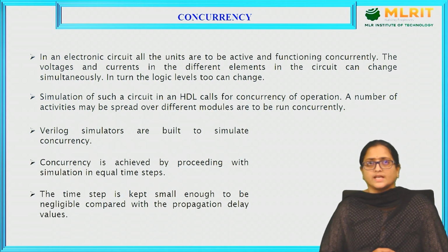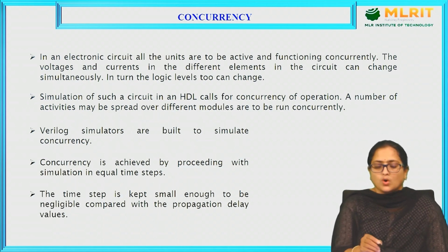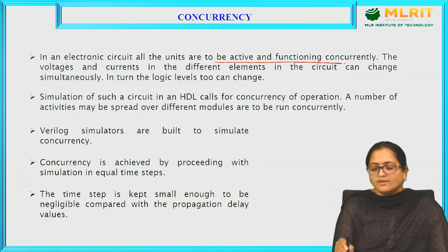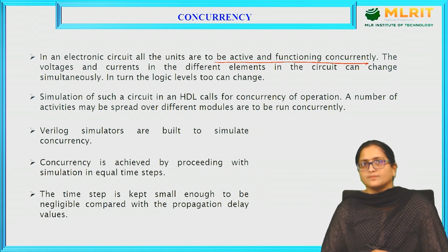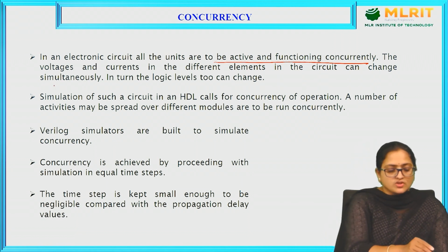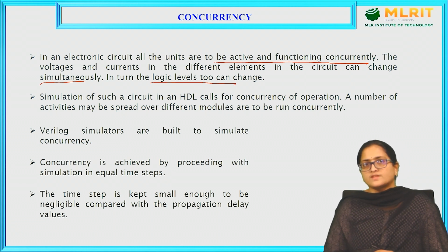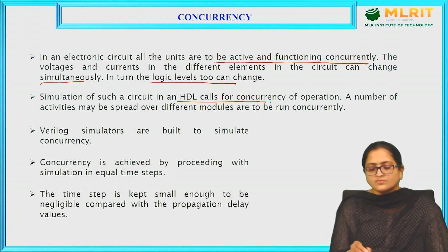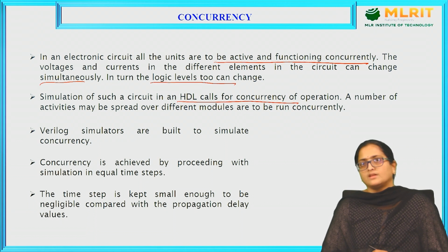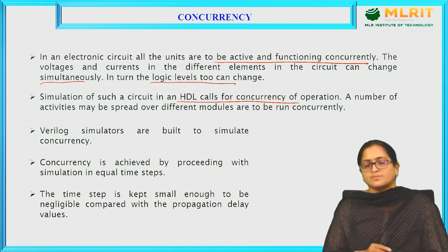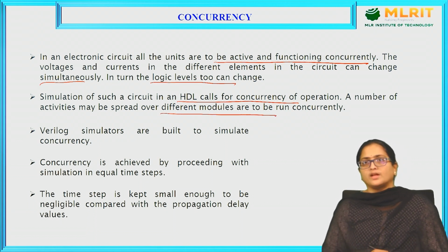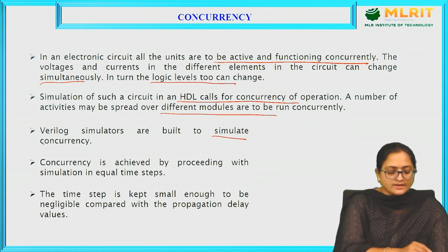First, concurrency. In electronic circuits, all the units ought to be active and functioning concurrently. The voltages and currents in different elements in a circuit can change simultaneously. In turn, the logic levels too can change. Simulation of such circuits in HDL calls for concurrency of operation. A number of activities may be spread over different modules, to be run concurrently. Verilog simulators are built to simulate concurrently.